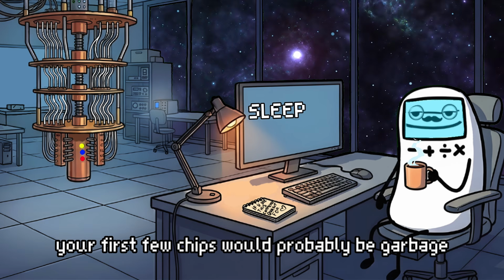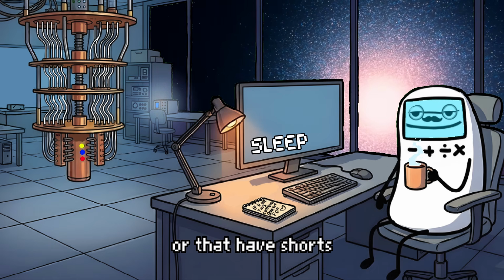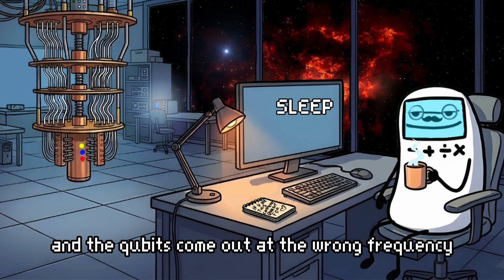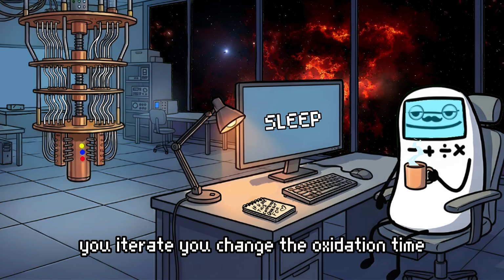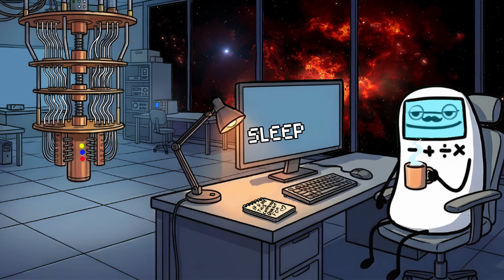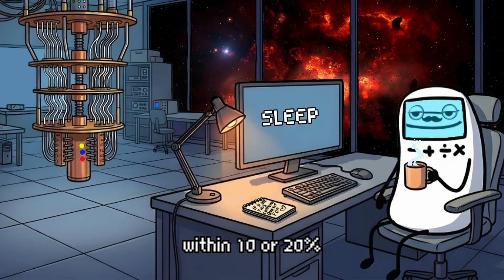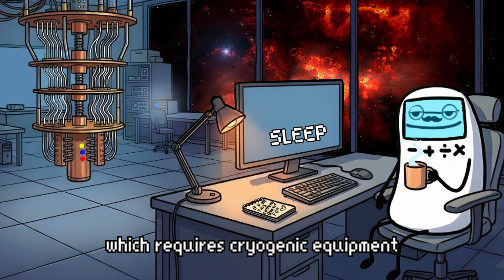Your first few chips would probably be garbage, with junctions that don't have the right resistance, or that have shorts, or that the whole process is just slightly off and the qubits come out at the wrong frequency. You iterate. You change the oxidation time. You change the beam current. You refine the resist processing. Maybe after a few dozen chip runs, you start getting junctions with the right resistance within 10 or 20%. Then you'd need to test your chips, which requires cryogenic equipment.